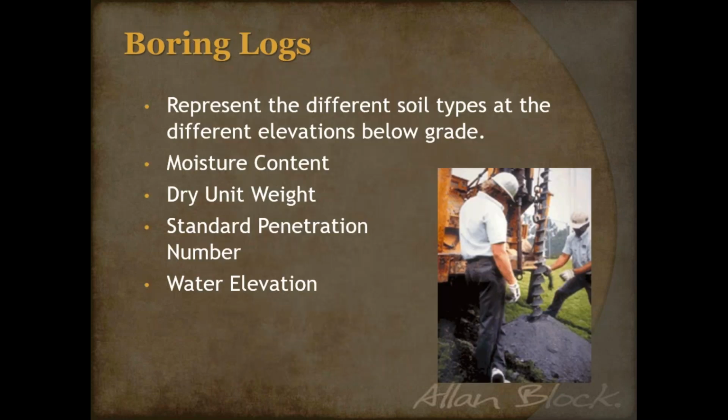A couple other things that we wanted to talk about is the actual grabbing of these samples, the exploratory drilling or test pits or whatever. I'm going to go on with the borings. And I always joke because that doesn't mean they're dull or not exciting. We're using some type of a hollow stem auger to kind of get to the different elevations. But once you have the samples, then we just go ahead and run the different tests. So we can classify the soil, we can grab the moisture content, we can get an idea how stiff it